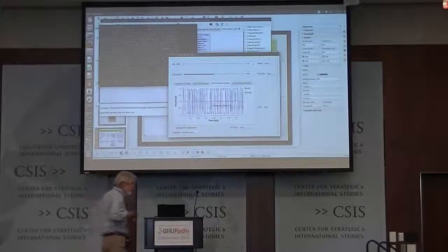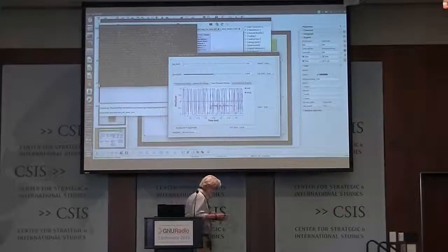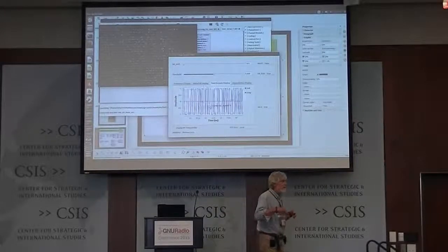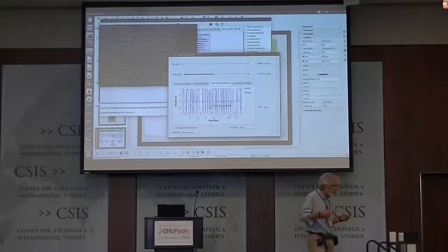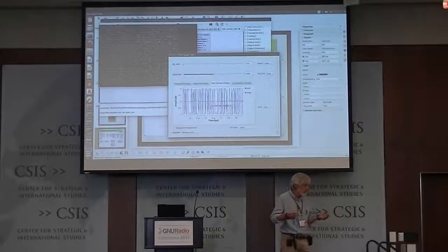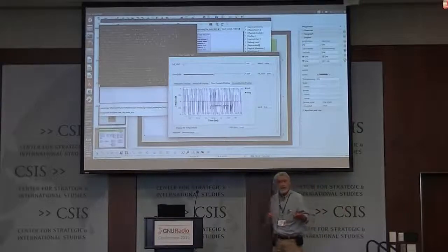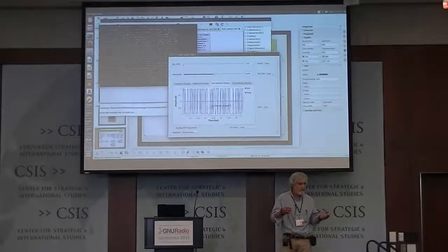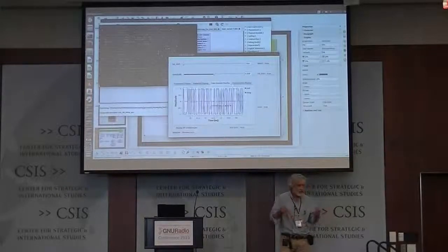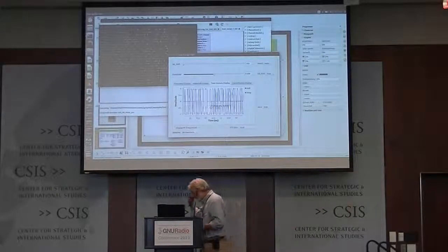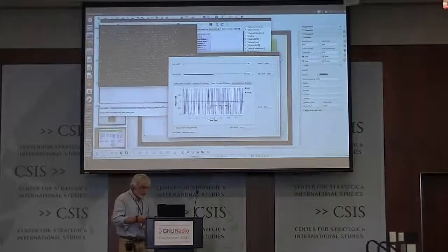So I give the students a file that has serial bits in it, and there is some mystery message in there, so that when they do their signal processing right, they get to see the message. They do not necessarily know the baud rate, they do not necessarily know whether a 0 goes into a -1 or a +1, and so forth, and they have to figure those things out.